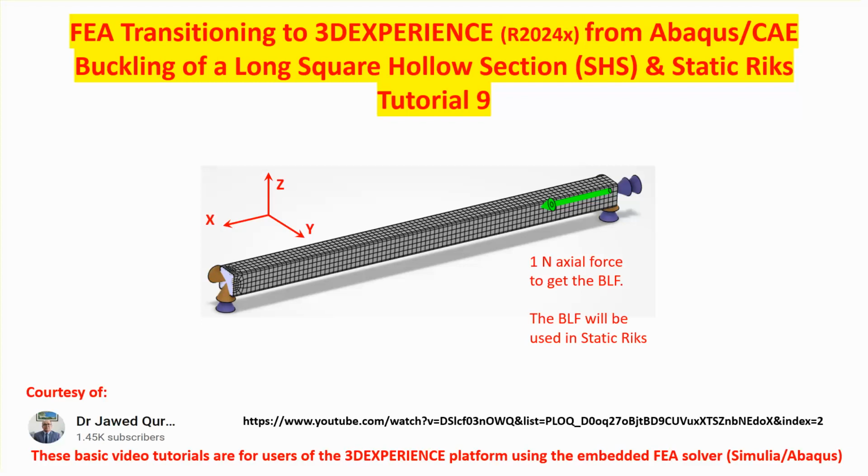So it's a tube basically with a square cross section, and he has done this problem entirely in the ABAQUS CAE program using a static Riks approach because it's more than finding the buckling load. You want to see essentially the nonlinear buckling problem.